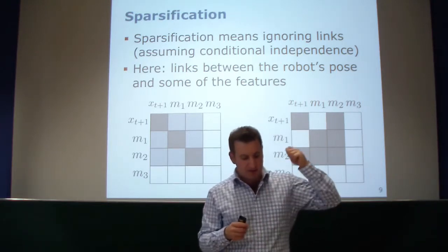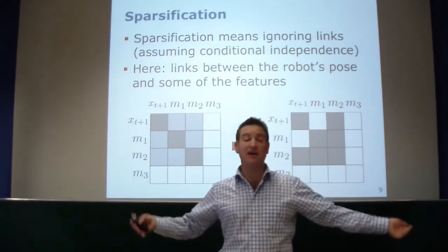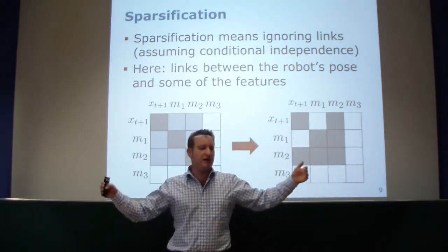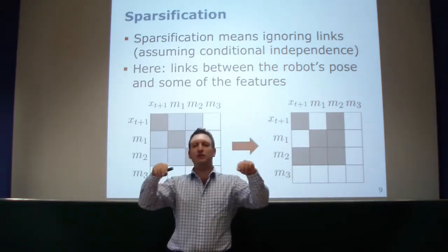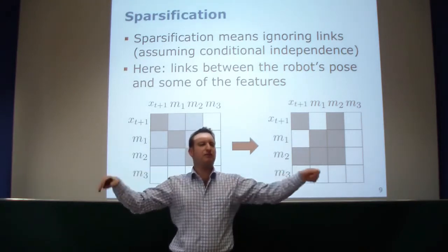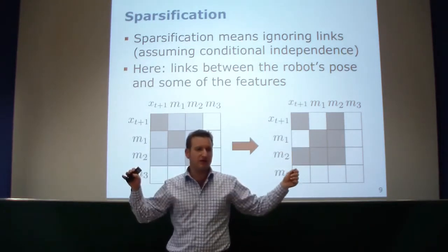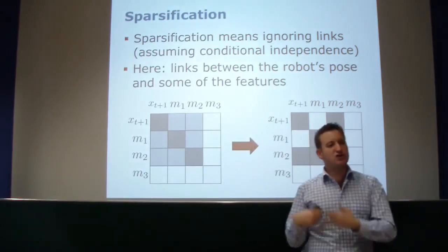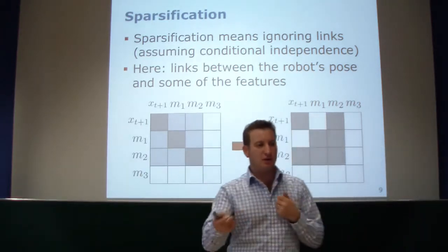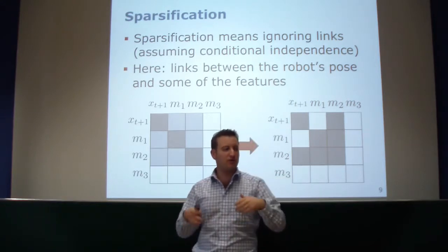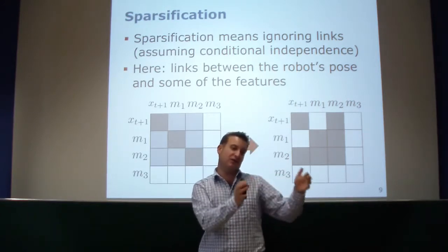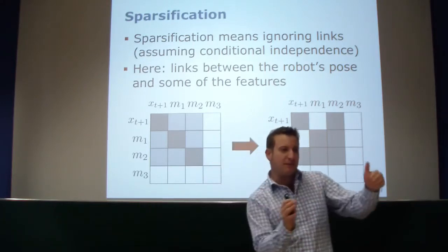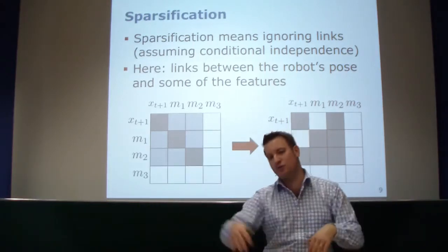links or dependencies between the robot and those features. So we just take, for example, 4 or 10 features. We say the expensive updates we only do based on the robot's pose in these 4 or 10 landmarks. However, if we move through the environment, we should change the landmarks which are directly linked to the robot's pose. And these are typically the landmarks in the vicinity of the robot that are observed by the robot. So I need to move my set of active features, and if I add a new one, I have to remove an old one.